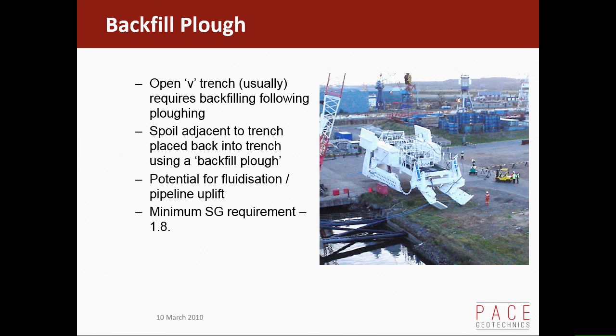So, would you try and coordinate that so you backfill when you were hydrotesting or something like that? Well, the ideal thing with a pipeline plough is to trench it empty, because it's easier to pick up, it lowers the stresses on the pipeline, and backfill it when it's flooded. But it's not too difficult to do that, because you've got one plough on the vessel for trenching, and then you go back to port, pick up another plough to do the backfilling, so you can manage that process reasonably well.